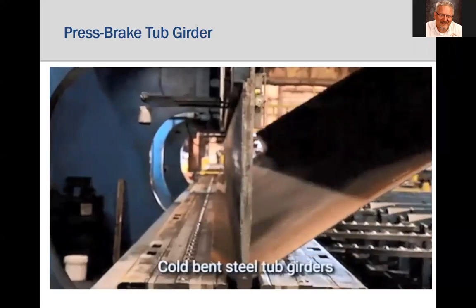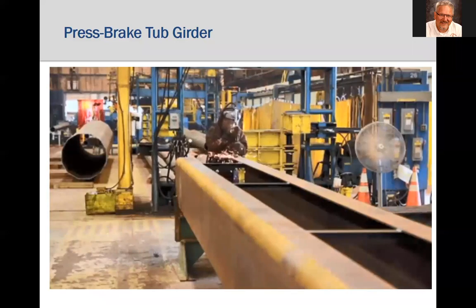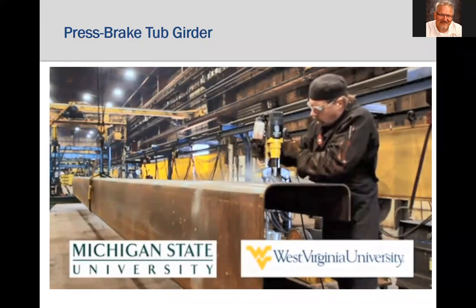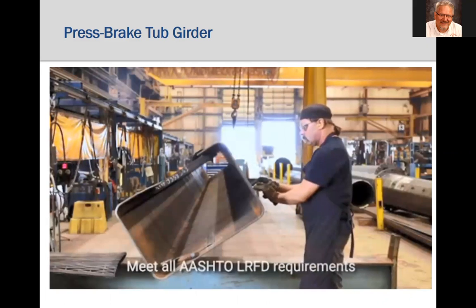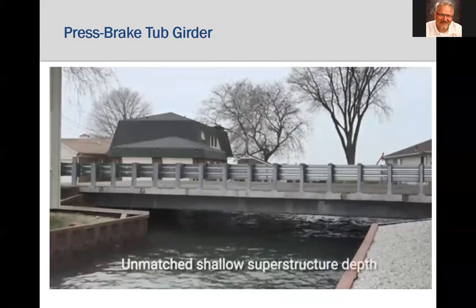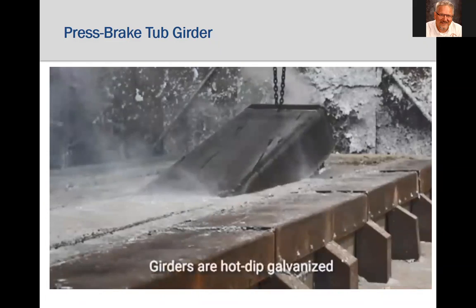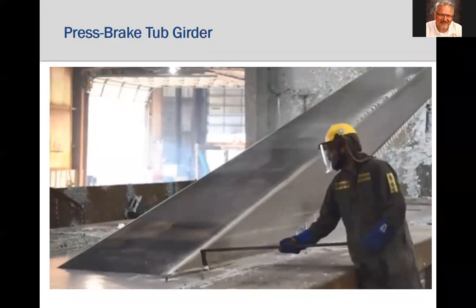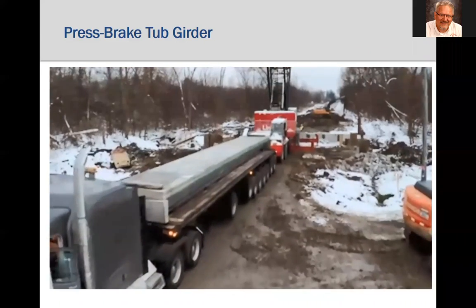The strength and durability of the bridge system continues with cold bent steel tub girders, which have been researched and tested by both Michigan State and West Virginia universities. These highly efficient girders meet all AASHTO LRFD requirements and offer an unmatched shallow superstructure depth for crossings in hydraulically sensitive areas. All girders are hot-dip galvanized, minimizing corrosion and further extending service life, ultimately providing over 60 years of maintenance-free protection. The prefabricated bridge units are delivered.